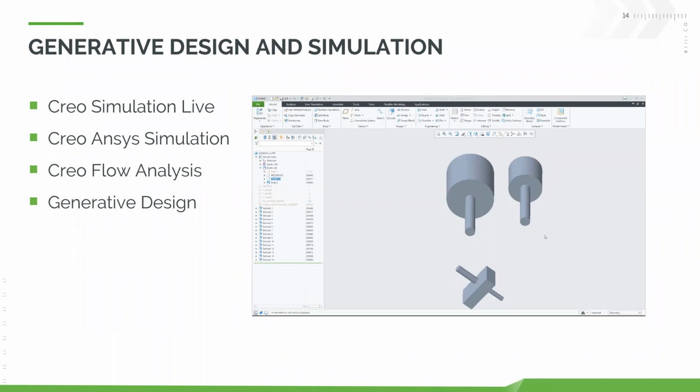And you can also now run an initial simulation before you start into a generative optimization. It's essentially like a sanity check, just making sure that your loads and constraints all look right, and then you can go do your generative run. So it avoids spending time trying to go through, solve things, and just ultimately realizing that you didn't have the study set up right initially. So something you can run as that sanity check before diving into an analysis.